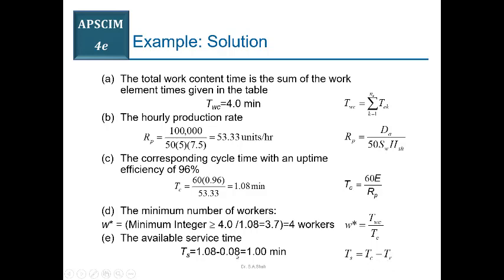Tr गिवन है 0.08. सो आपके पास जो एक्चुअल अवेलेबल टाइम होगा दैट इज़ 1 मिनट. थ्योरेटिकली आपने फाइंड कर दिया है कि अगर ये प्रोडक्शन रेट आप अचीव करेंगे तो यू विल अचीव this particular demand, and for this production rate you must have a cycle time equal to 1.08 minute, but the actual cycle time that will be available to you after repositioning of the work pieces, after repositioning of the workers, the actual available time for machining will be 1 minute.